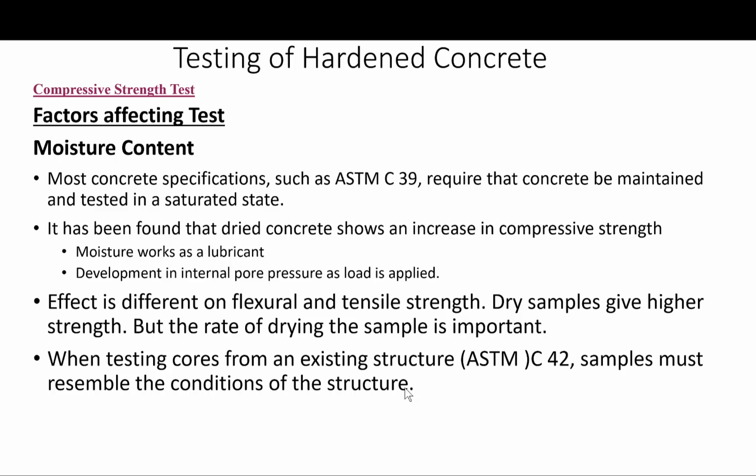It may have something to do with the change in the structure of the calcium silicate hydrate on drying, or it may simply represent a change in the internal friction and the cohesion on a macroscopic scale. Moisture may have a lubricating effect, allowing particles to slip by each other in shear mode easily. That could be the explanation.